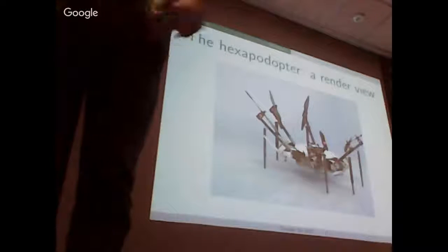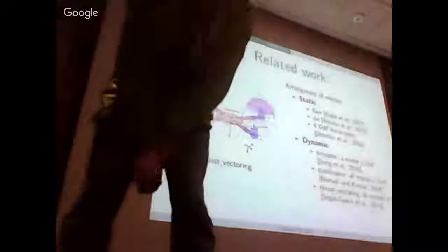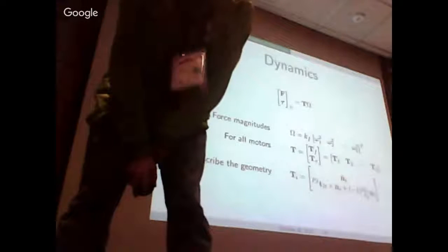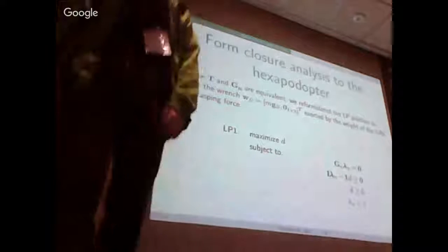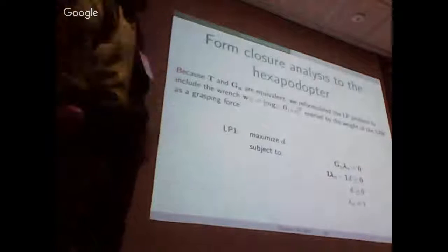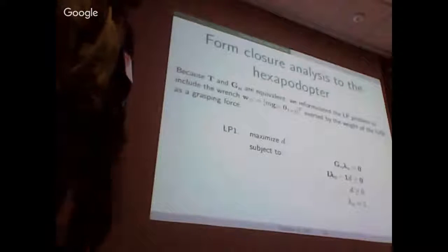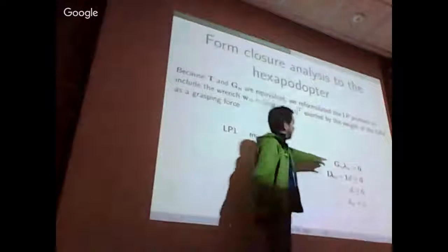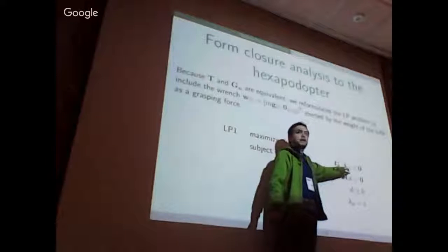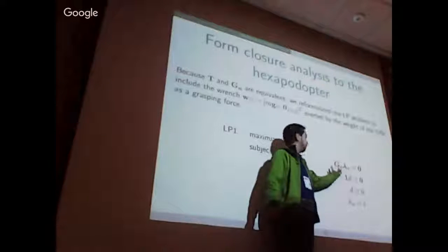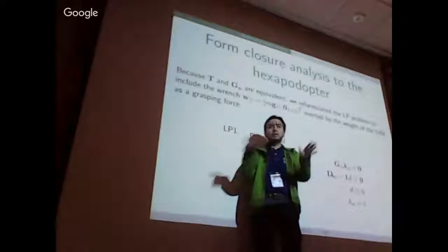One more. Okay. With the optimization problem, can you put the constraints? You say you want to maximize. Yeah, exactly. So this, or you put the first one, I think, is the force closure satisfaction or constraint. The first? Yes. This one is the equilibrium. Given a coefficient for all forces and the grasp matrix, the product has to be 0, so the wrench around the body is 0.